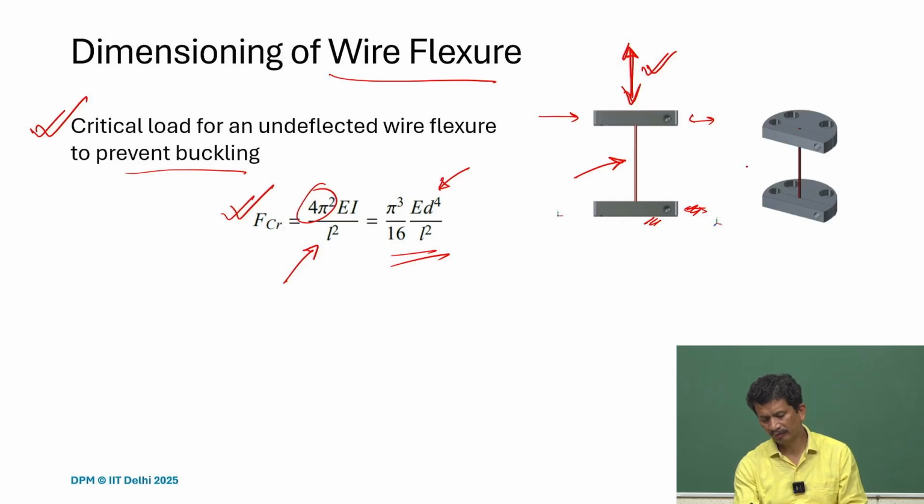One of the things is when you are working with these small diameters, it's very difficult to assemble. So for that we made these slotted features here, and you can see a slot and a hole here, and it's assembled with a threaded screw, and we clamp it from there. So these are some small features, and we have to take care of that.